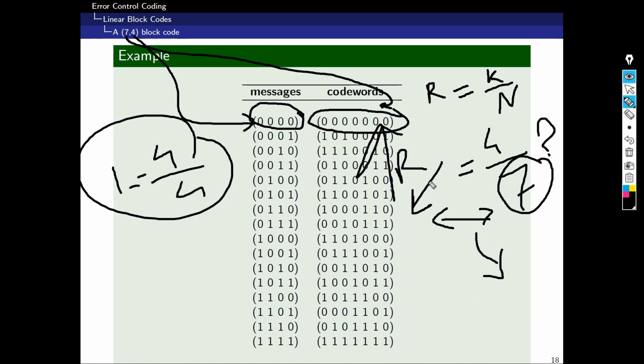You can decrease the bit error rate by decreasing the code rate. This means that instead of using 4 over 7, I can use 3 or 2 over 7. However, if my system is very sensitive to throughput and I want to increase the throughput as much as I can, then I can increase the R value and make it like 6 over 7.